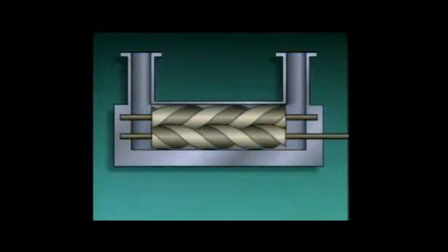This pump uses screws to create the rotary motion that displaces the liquid. This pump consists of a casing with a suction port and a discharge port. Inside the casing are two screws. One screw is the driver, and the other is an idler screw.